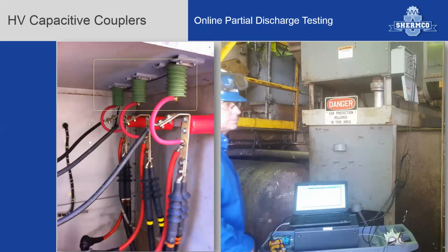So again, depending upon what level of sophistication you want to get into, it could be an unsophisticated node where a technician comes out on some scheduled basis and runs a scan to trend the condition of the insulation or any PD activity, or it can be a smart node and could actually be doing the measurements and text messaging you or emailing you if thresholds are being exceeded and a call to action is being required.